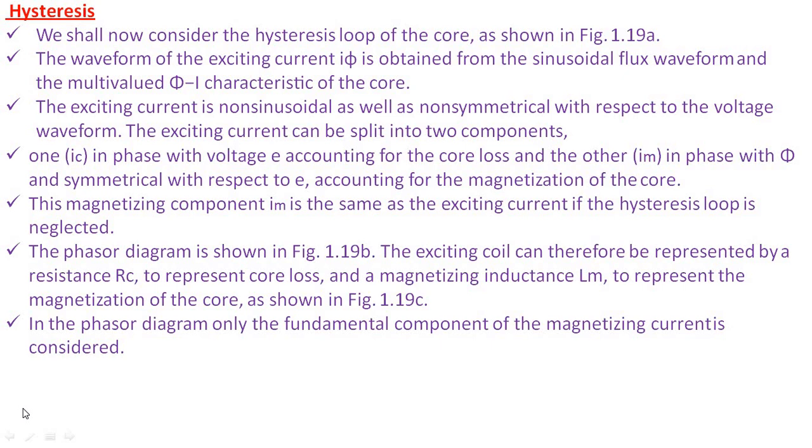The waveform of the exciting current is obtained from the sinusoidal flux waveform and the multi-valued phi-i characteristics of the core. The exciting current is non-sinusoidal as well as non-symmetrical with respect to the voltage waveform. The exciting current can be split into two components.